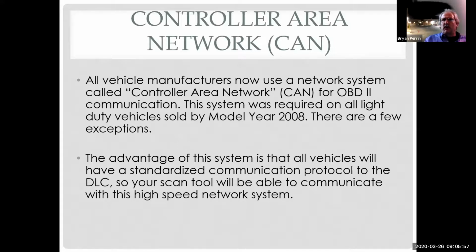So I can talk to a Mercedes or a Maserati. It doesn't matter. I can talk to that OBD2 portion of the vehicle. Not necessarily all the modules, not necessarily the manufacturer side, but whatever's on that OBD2 network, which is probably going to be my engine, transmission, probably airbags, ABS, maybe instrument cluster. But some of them only have 1 or 2 modules on that OBD2 network. Other ones will have several modules. So it kind of depends on how they did the network topography.